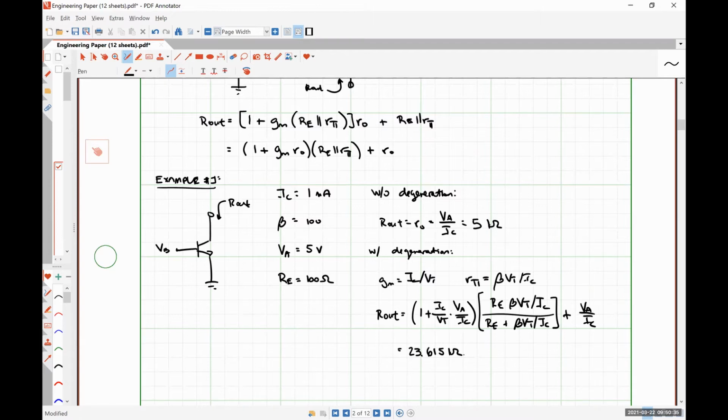There is, however, a trade-off. If we are going to use an amplifier, so we allow Vin to have some sinusoidal value or whatever, we know that we need a specific collector-emitter voltage in order to keep the transistor operating within the forward active region. If we allow VCE to get below VBE, we're entering into soft saturation, and our output isn't going to follow our input exactly. We're going to see some distortion.